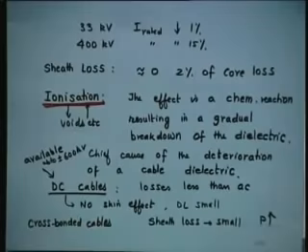So, DC cables also are there. It is not a fiction, it is reality, and they are available up to plus minus 600 kV. Losses are definitely less than AC. Whenever you are asked what are the advantages of anything DC over AC, there is no skin effect. Dielectric losses are also small, sheath losses are smaller, and what is cross bonded cable?